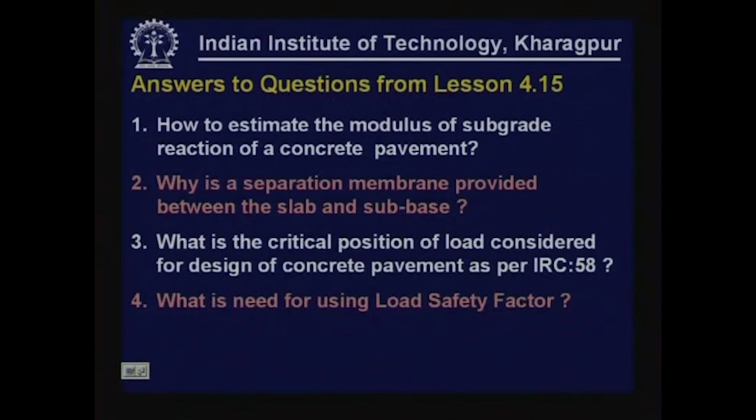Why is a separation membrane provided between the slab and the subbase? If you have understood the procedures that were discussed for PCA and IRC 58 design procedure, many concepts are similar, but PCA does not recommend use of plastic sheet between the subbase and the slab, which would make it a smooth interface.